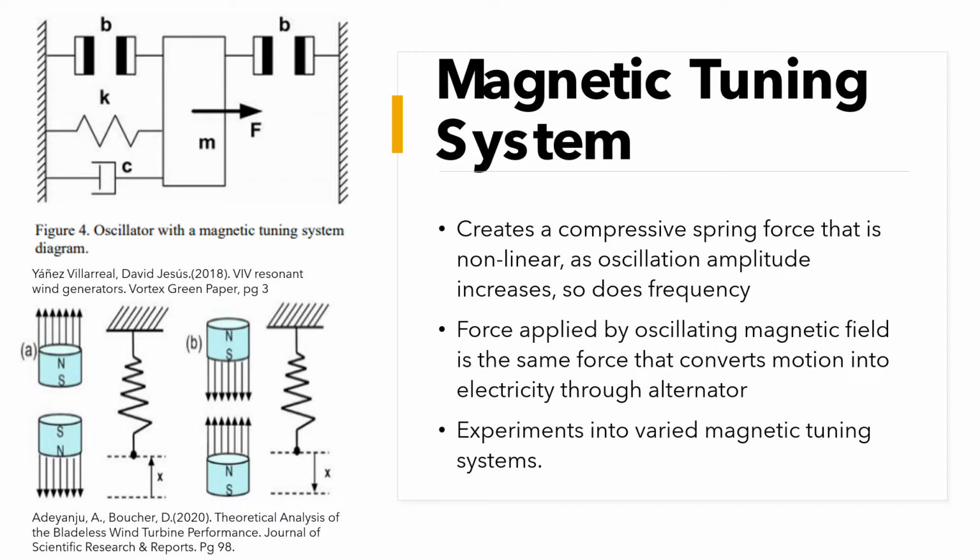This allows the turbine to operate at much lower fluid velocities than the standard damped harmonic oscillator model because of the nonlinear spring force that exponentially increases the amplitude of the lower oscillation frequencies until they can reach the lock-in zone resonance of the structure.